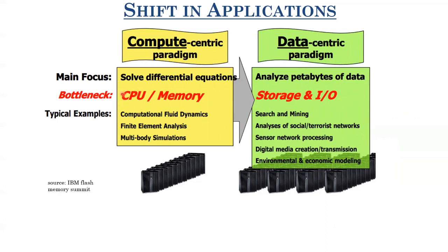There the bottleneck used to be the interaction between CPU and memory. As I'll tell you later also, modern CPUs follow a von Neumann architecture, where the processing unit, or the ALU, and the memory are two different blocks. So whenever you have to process anything, you have to send data frequently between the logic processing unit and the memory. That is heavily energy intensive, and it also adds to the latency. Because of that, your system is pretty slow, and the clock frequency has saturated over the years.